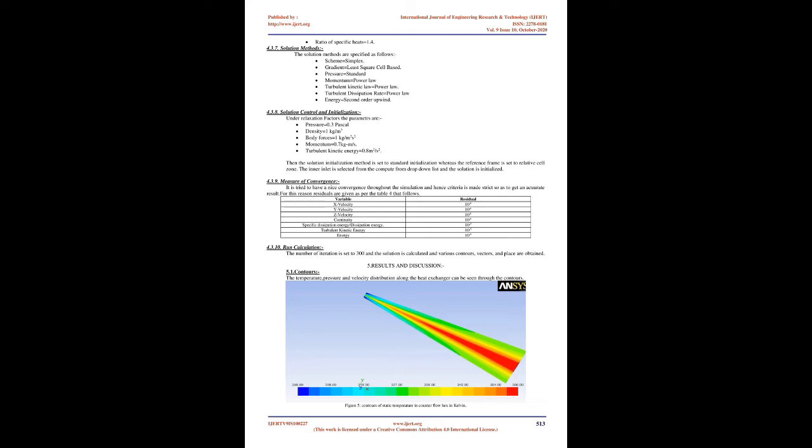Fluent is a CFD code used for flow modeling applications. Fluent needs some input data and domain drawn from various software like Gambit, Catia, Pro/E, and other design software. Now Fluent can analyze the given domain with boundary conditions and solve the governing equations for the flow given the different parameters. Steps for analysis in Fluent are: A.